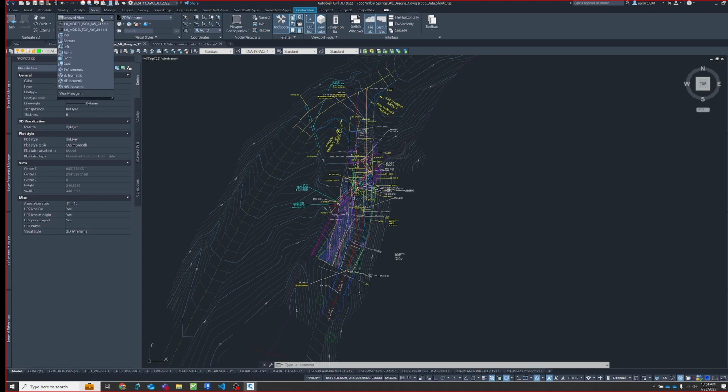And in this one, I did save a couple. I usually start with saving a view state that is the top-down view, because we work in Civil 3D mostly in the top-down view, profile and section view as well. But I do that because that's my home base starting point, and that is this view here. And then let's say I save, in this case, just one isometric view looking at the surface. So let me go to that view. It'll take me to an orientation if I don't crash CAD, and it'll rotate it, and it'll show a different type of view.